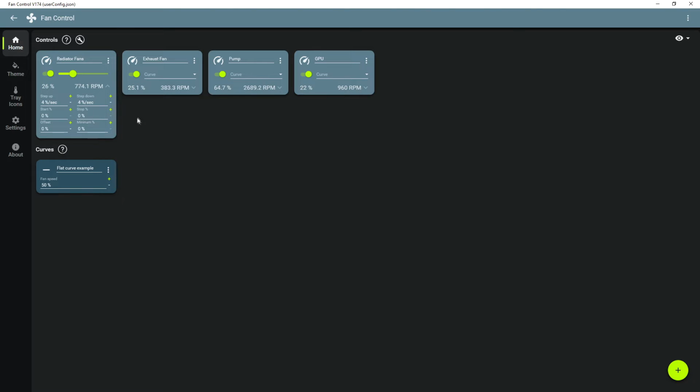Because sometimes there might be certain fans you may not need them always running. That's not always needed. So that might be something to look out for when you're choosing your fans. Start and stop is pretty much, yeah, if you're going to set up fan stop on it. You can set a limit where basically under it, it will just stop the fans. Basically, it'll go to 0%.